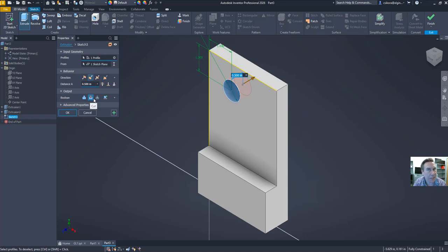Really, our best option here is probably to remove that. That's the intent of the author. So anyways, let's leave it at cut. Now there's another step here or segment, and this is cross-platform with any CAD system, something called design intent. Design intent is your plan on how you would like this to update to where it's beneficial and easy. So for example, right now it's set to 0.5 for this hole.